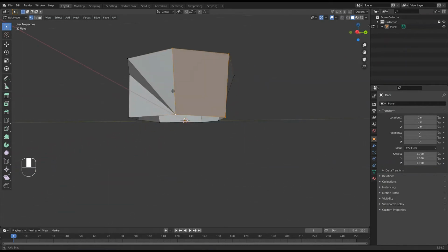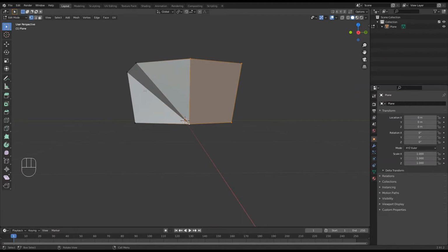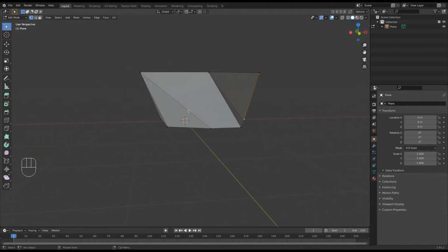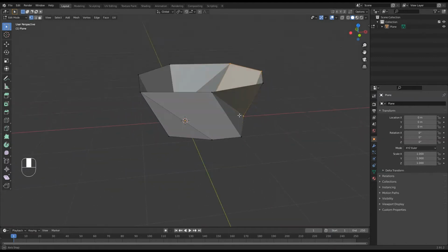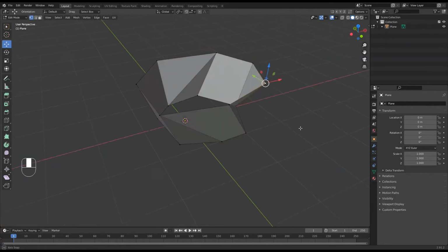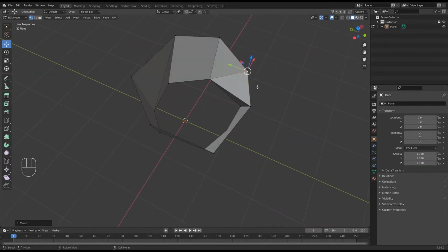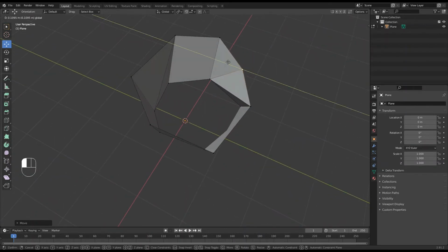With clay 3D printing, the clay wants to fall down while it's being printed, so you don't want too dynamic angles. These angles here are right, but in here it's a little bit dynamic. So I think what I'm going to do is go to my move tool, select that one, then I can just move this in a little bit and possibly a bit in that direction too.